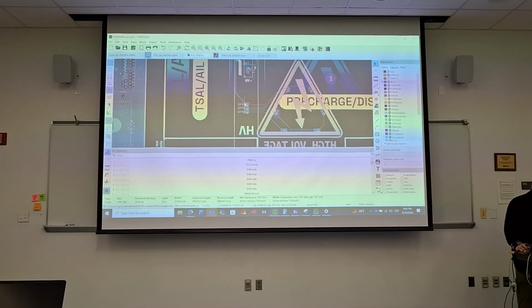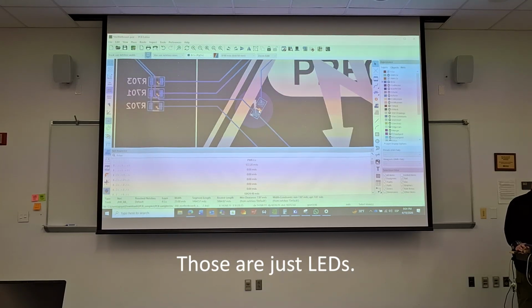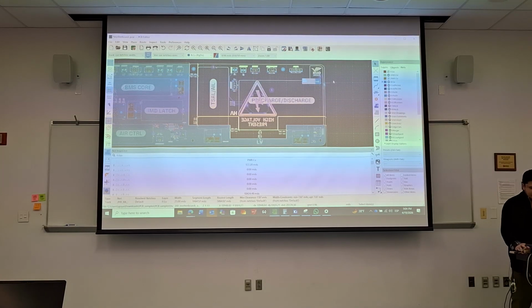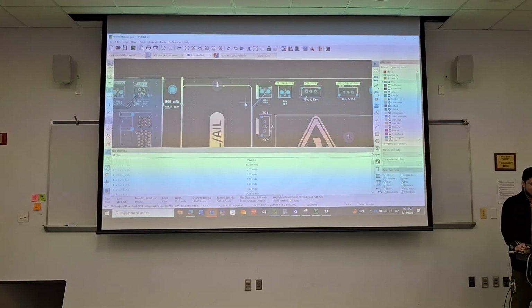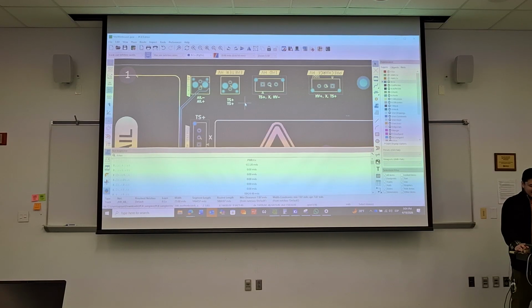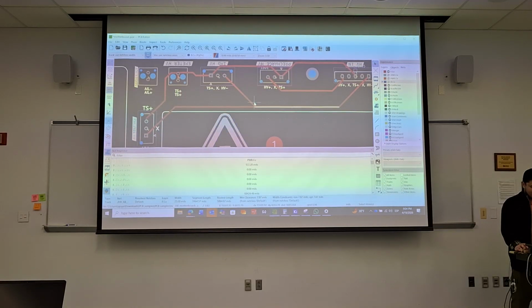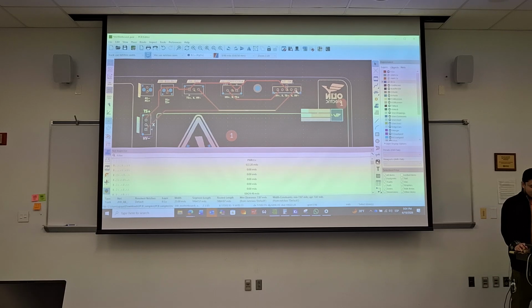And then these, I assume sense lines? Oh, these are LEDs. Yeah, I just don't like that there's absolutely no ground. There's no return current. Like, where are you closing the loop? I guess you technically are routing it, but it's just such a huge loop because basically, instead of keeping the loop localized underneath the trace, you have to go all the way around.